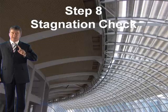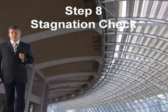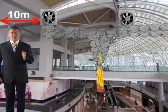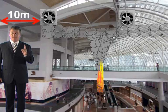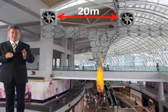Now we need to know, where do we locate them? So where are we going to put our ventilators? Now don't forget, before you carry this out, you've got to check the next step, step 8, which is the stagnation check. And again, it only applies to natural ventilation, and it means that ventilators cannot be more than 10 metres from the side of a room and no more than 20 metres apart. And this is because the smoke, again, may stagnate in between them. So this is for natural ventilation, not mechanical. You carry out a stagnation check.